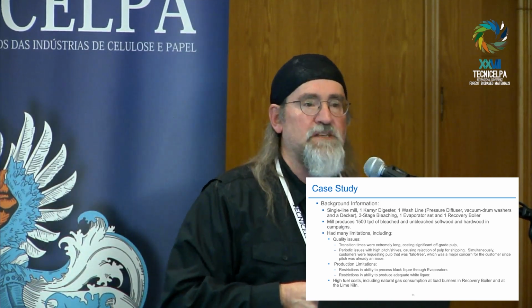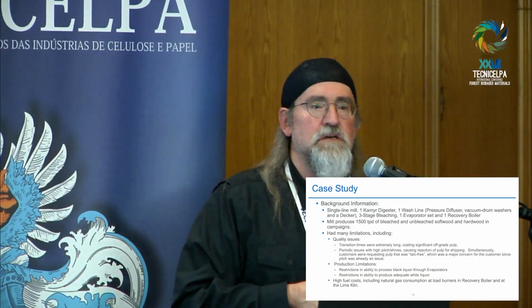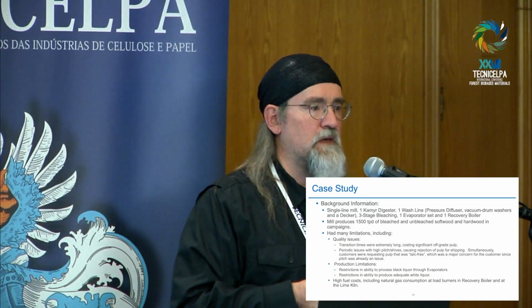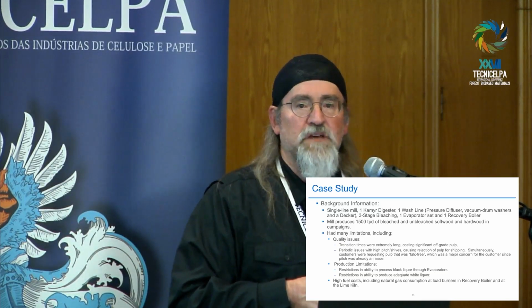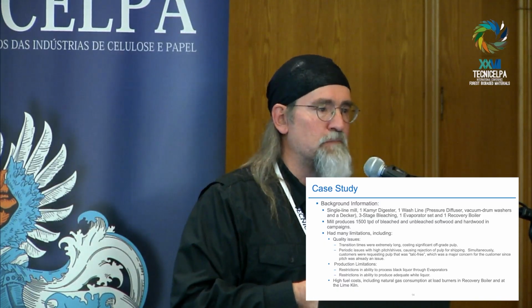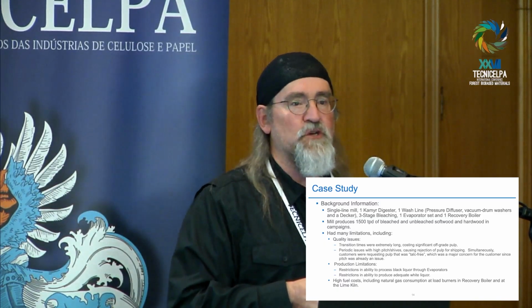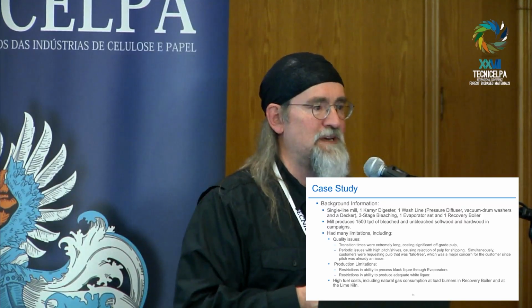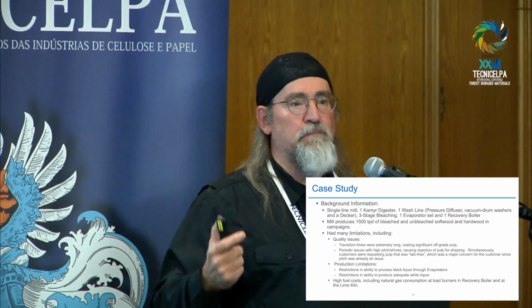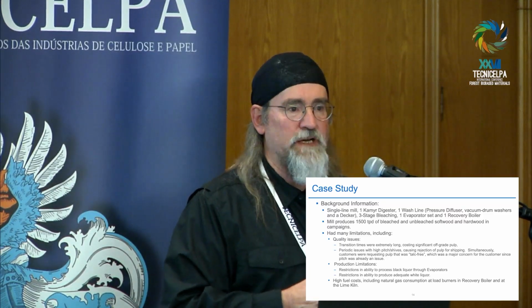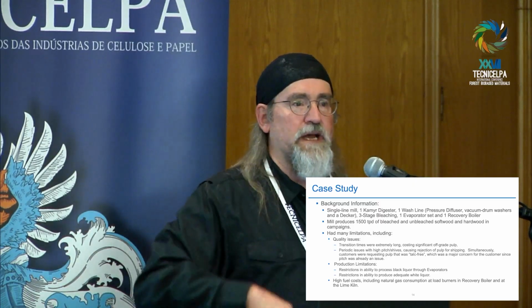Two of the grades are unbleached, softwood and hardwood, okay? Four of the grades are bleached hardwood, bleached softwood, and bleached co-pulped blended pulp, okay? You talk about a mess for a liquor chemistry cycle, right? It's horrible because I got 100 kappa, next thing I know I've got 20 kappa. Okay, sometimes the chips are mixed.